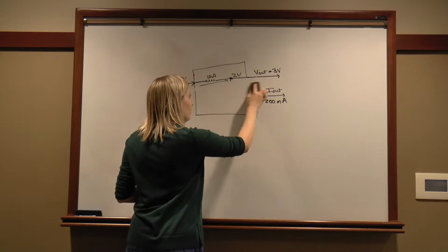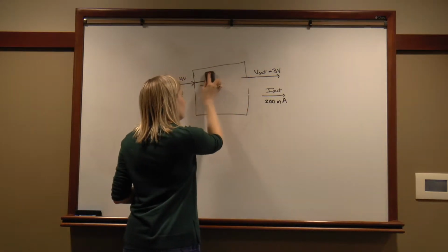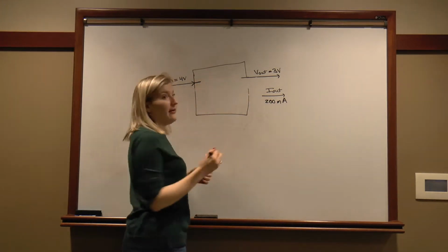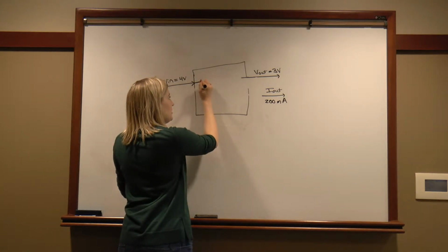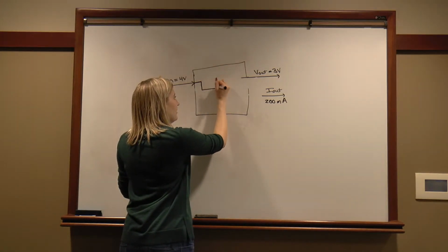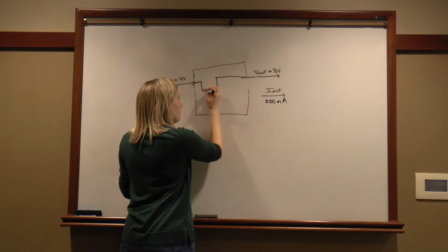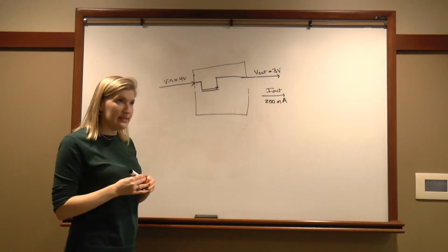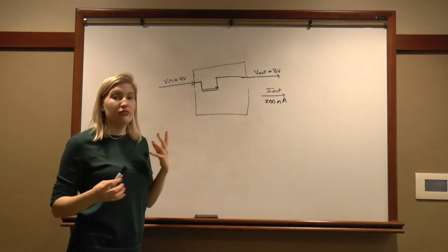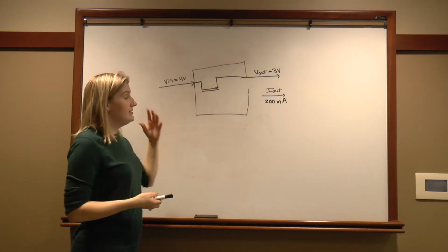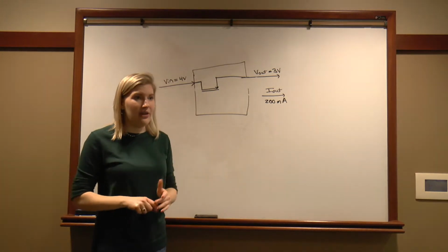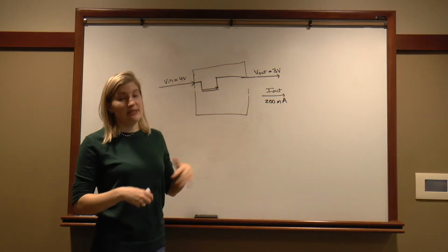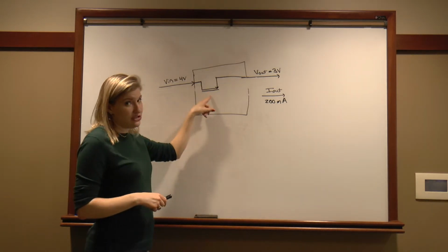And we're going to jump into our linear regulator. So now instead of this resistor up here, we're going to insert a FET, and here we're going to use a PMOS. And we are going to operate this PMOS in the linear region. So it's a voltage-controlled resistor, essentially. And this is opposed to the saturation region where we have fully enhanced our channel and our RDS(on) is as low as possible. Here we want to be able to change the resistance on the fly by adjusting this gate voltage.